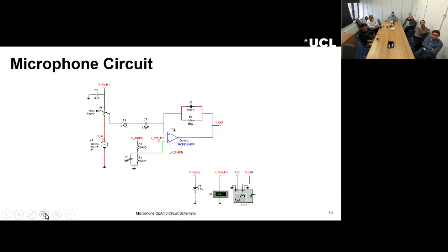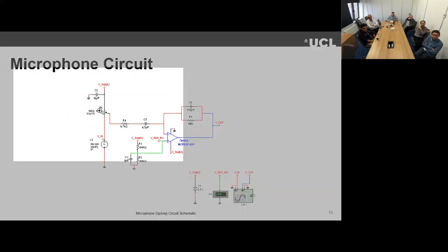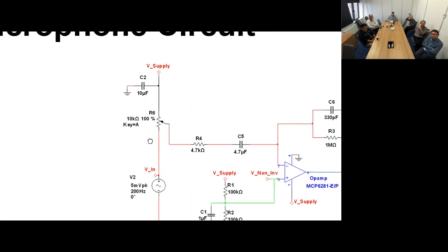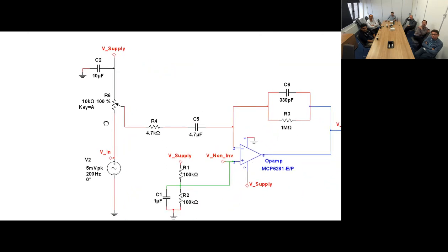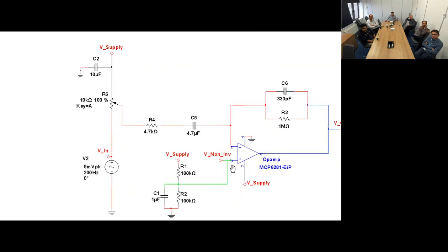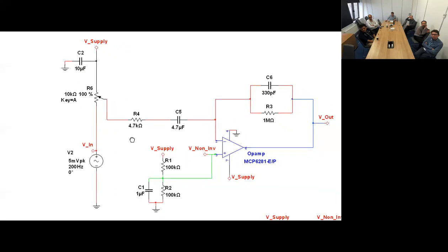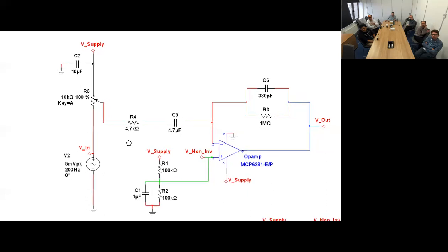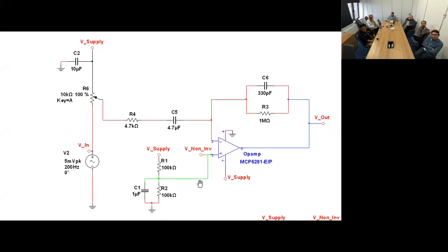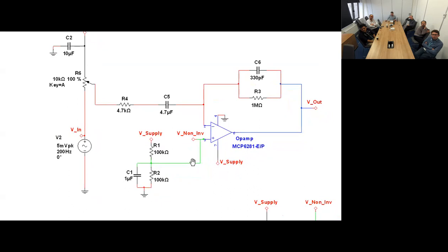And here we have some op-amp circuits for our transducers. For the microphone circuit, we use an inverting op-amp circuit, which has a logarithmic potentiometer, which makes it quite flexible and gives us the chance to adjust the gain. So it can still be used with different devices.